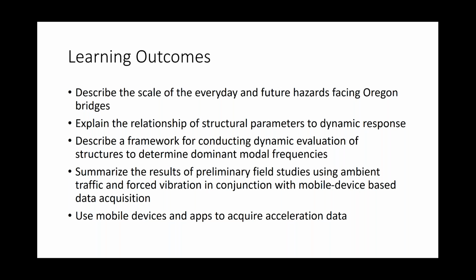Definitely want to give you the results of some of our preliminary field studies. We've looked at ambient traffic and forced vibration, in addition to some periodic jumping with the team of graduate students. And a lot of our data acquisition has been based on mobile devices. So I definitely want you to leave with an ability to use your own mobile device, identify an appropriate app to acquire acceleration data so that you might be able to make some observations of your own.